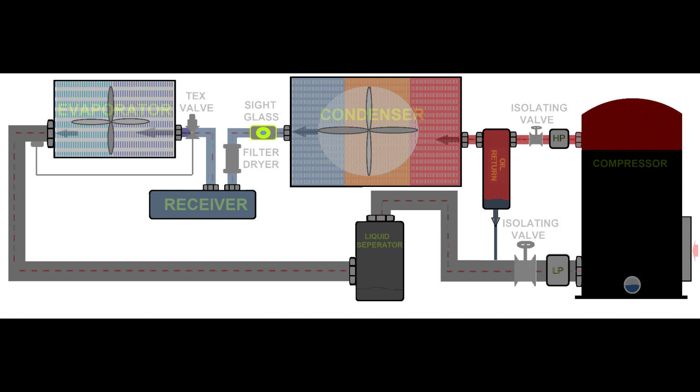What does superheat mean? As you will see, the thermostatic expansion valve has a little bulb underneath the pipe at the evaporator exit. At that point it controls the liquid so that no liquid, or excessive liquid quantity, goes out from the evaporator. And that's because we don't want liquid to come back into the compressor. Otherwise we will destroy the compressor.